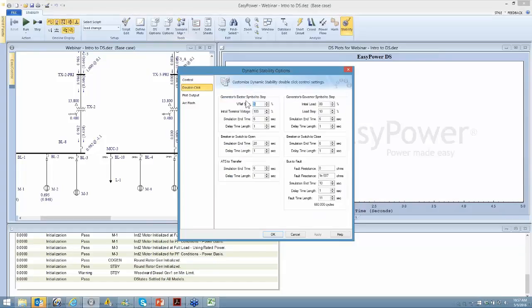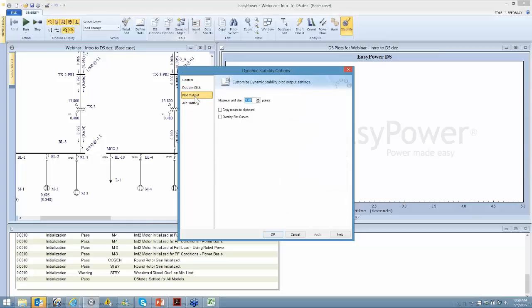So as we were double clicking on different elements, this is what determines what's shown in what the operation is and what's shown in our auto plot here. And then when we're going to calculate arc flash, we're going to use arc flash simulation for faults. We're going to use 100% arcing current. I'm going to go ahead and apply this.